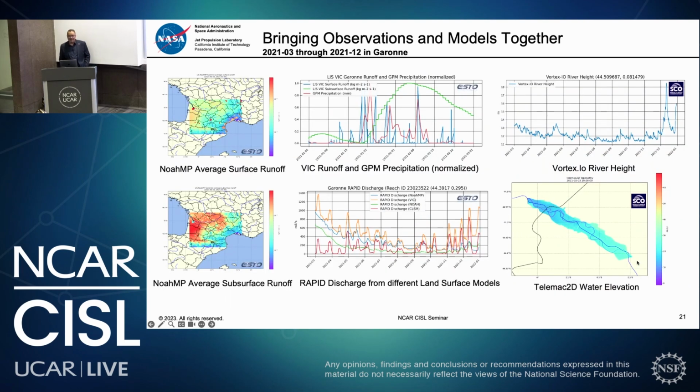So to put all this together, and again, I'm not a scientist, so I learned this as I developed the system by working with some very, very smart scientists. To look at flood, you want a model that looks at the runoff. When it rains, water runs off, either surface runoff or subsurface runoff, and that can tell us where the water is heading. But then you also need a discharge model that tells you about the stream. When you have this much water going to the stream, based on the topography and the river network, where are the sensitivities? That's the second model.